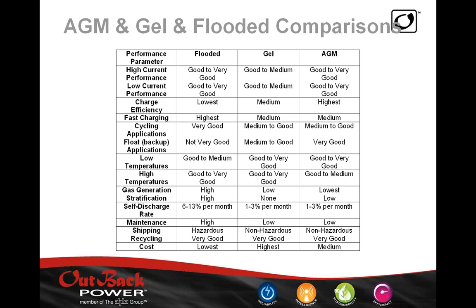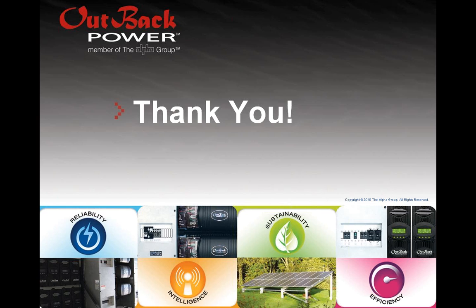For example, the nominal self-discharge of gel and AGM batteries is 3% per month, and this is independent of whether you put them on wood or concrete or whatever material the batteries happen to be resting on. They self-discharge because of the chemicals they have inside. I'm going to leave this table here available for your review.